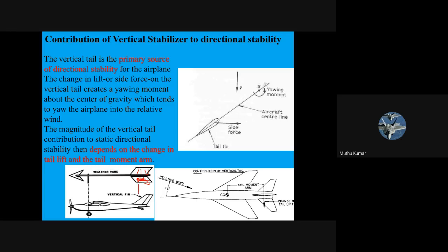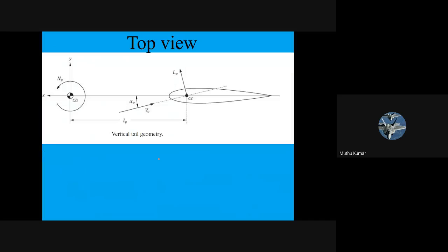The equivalent for us is the vertical stabilizer. So the vertical stabilizer does this task. In top view it is exactly an aerofoil, exactly a wing, a shorter wing. That is all, nothing else. It produces the restoration force to give the right moment.